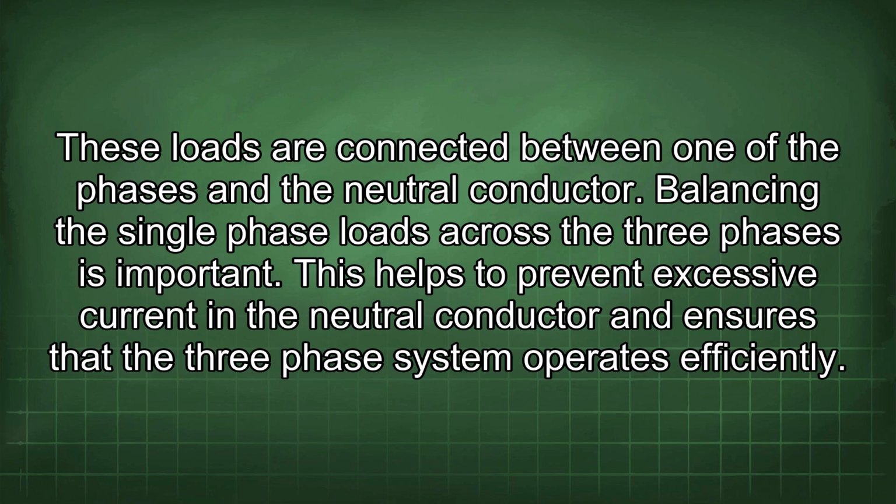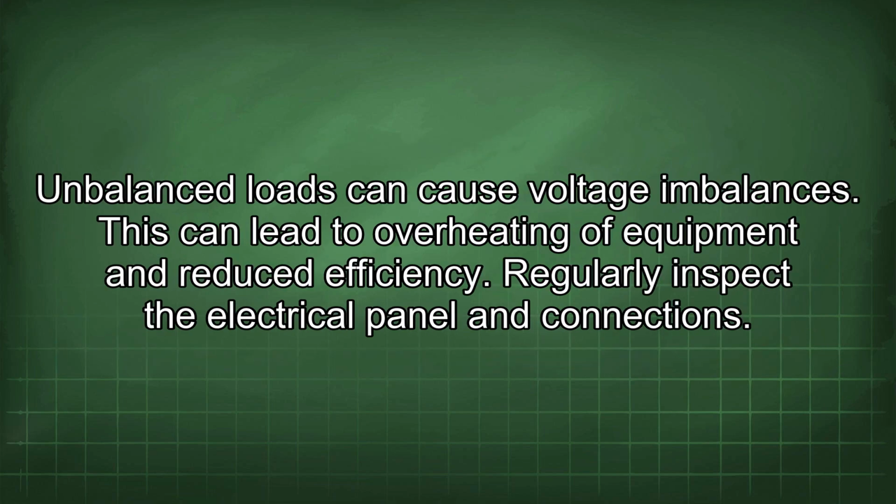Balancing the single-phase loads across the three phases is important. This helps to prevent excessive current in the neutral conductor and ensures that the three-phase system operates efficiently. Unbalanced loads can cause voltage imbalances. This can lead to overheating of equipment and reduced efficiency.